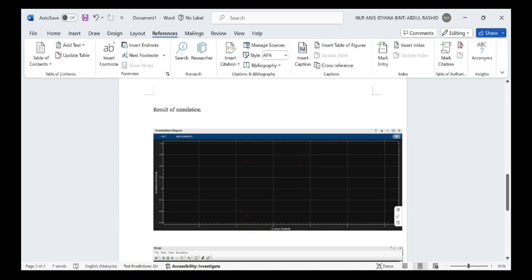The presence of four distinct points or stars in your constellation diagrams indicates that the modulation likely involved 4QAM. In 4QAM, each symbol represents a combination of both in-phase and quadrature components. The 4 points on the constellation diagram correspond to the different combinations of amplitude and phase for these components. Each point represents a unique digital symbol.